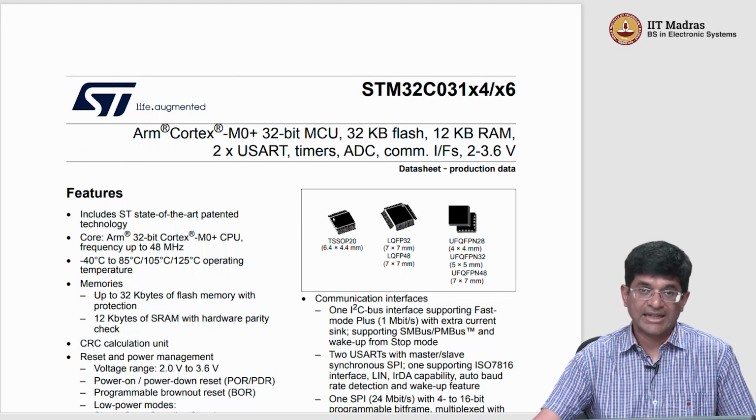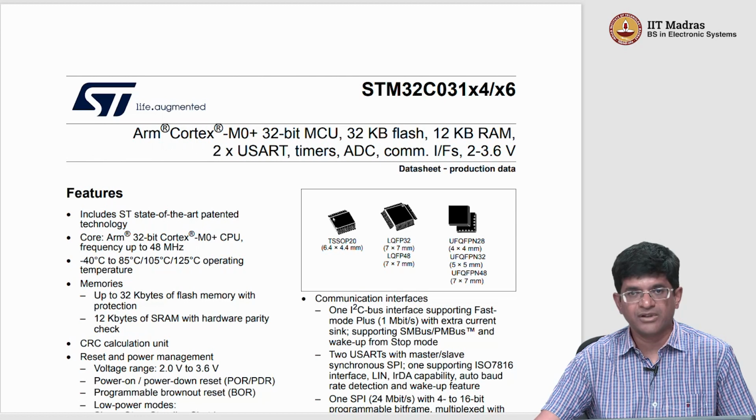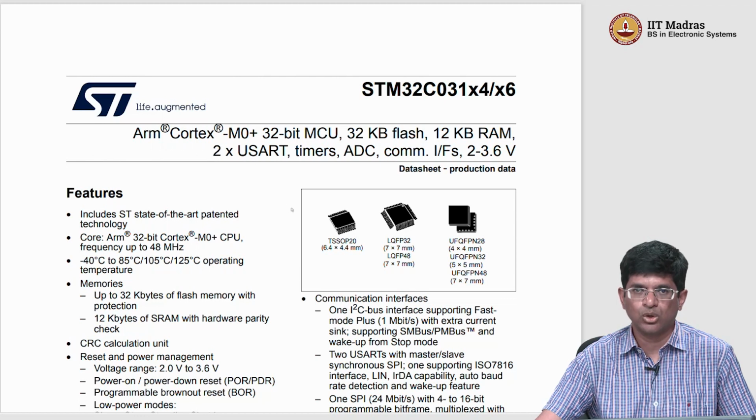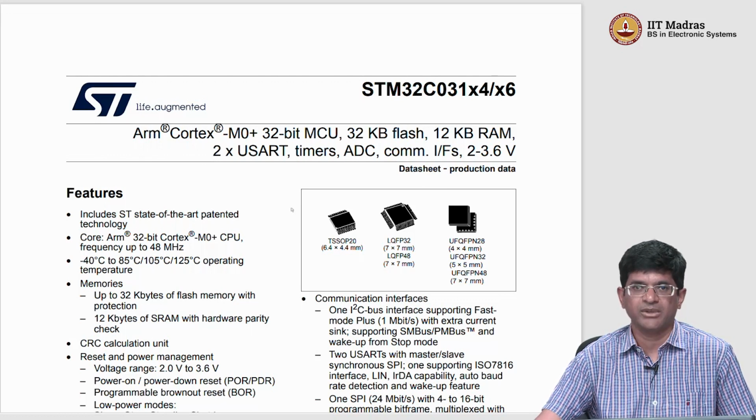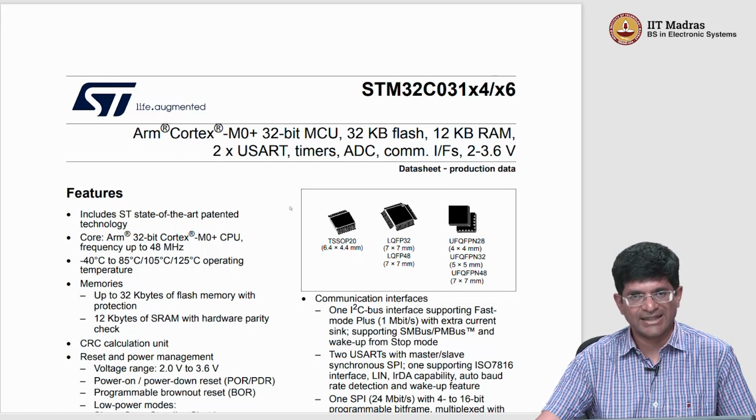Through-hole components are very rarely used in PCBs. They can only really function at fairly low speeds compared to what you need, and it's relatively rare to find through-hole type microcontrollers, except for things that are specifically targeted to run at low speeds, in which case they might even be available in packages that can directly fit on breadboards. It's not unheard of. In fact, the Atmega series, for example, has things that can directly be plugged into breadboards, and that's perfectly usable. But whenever you are designing a board and you want to have more functionality, the most common forms are some kind of surface mount devices.